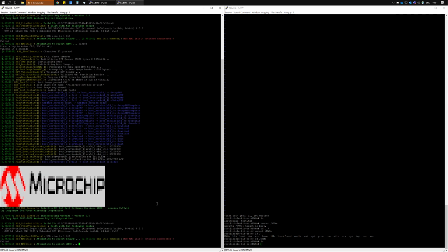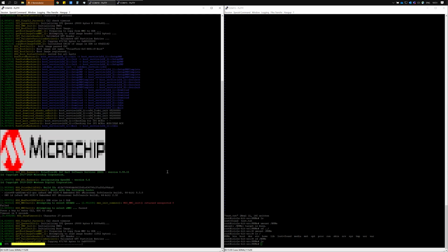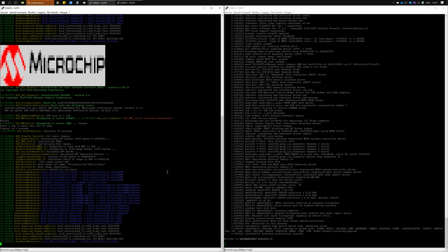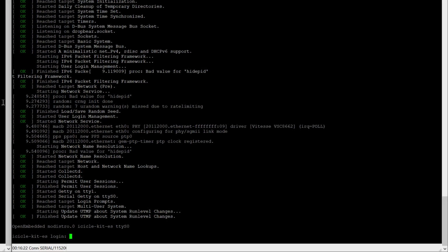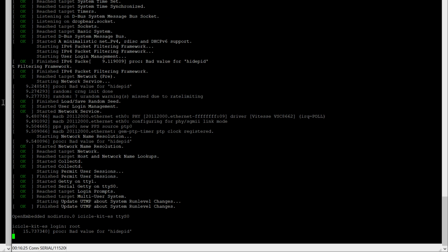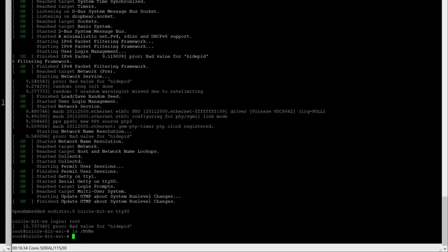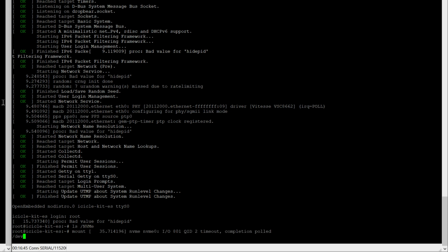You can see the HSS has started back up again here and is reloading the Linux image. Now that Linux has started up once again, we can log in with root. Then run another ls of the nvme directory, and we can see that it's still empty. To test that our files have actually been kept on our drive, mount /dev/nvme0n1 to the /nvme directory once again.